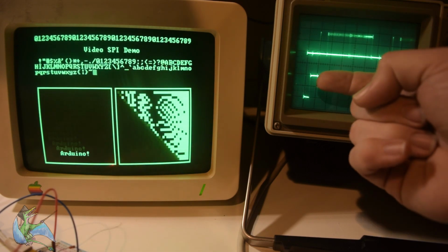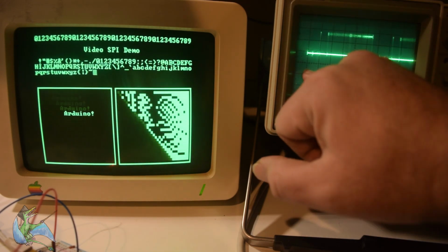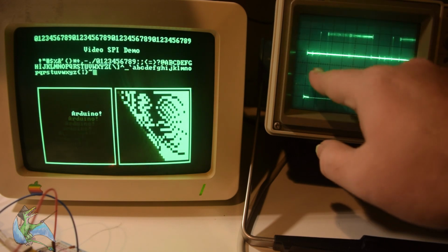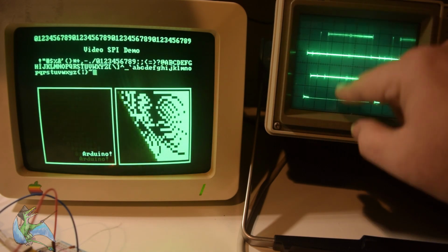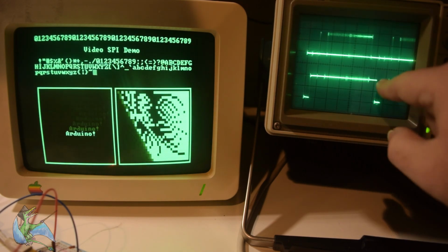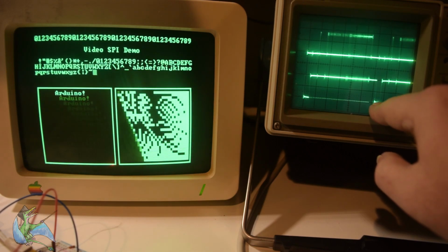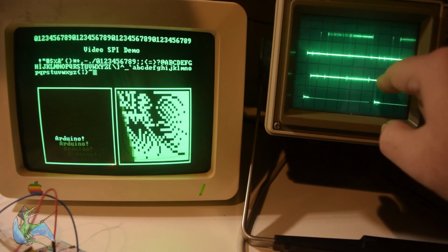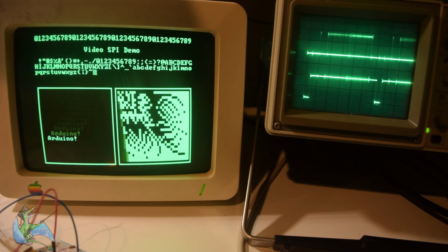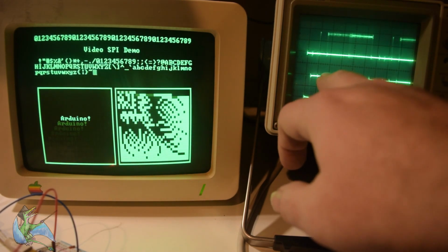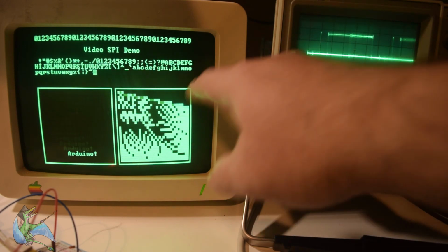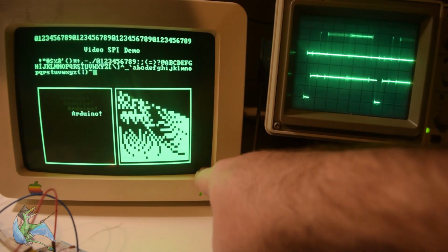So this part is the long period, the active video part is down at 0, and then there are these 4.7 microsecond intervals that get flipped back up to the 0 point to make sure the monitor doesn't lose sync. Now this happens for 3 lines, so basically you get to 262.